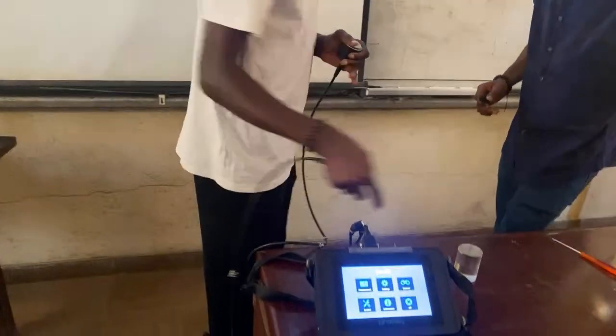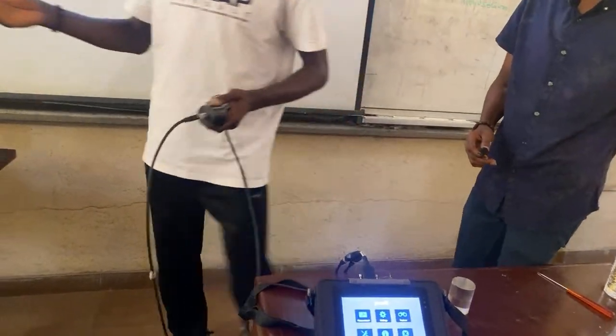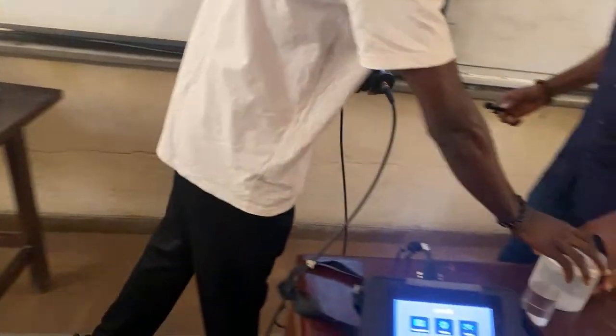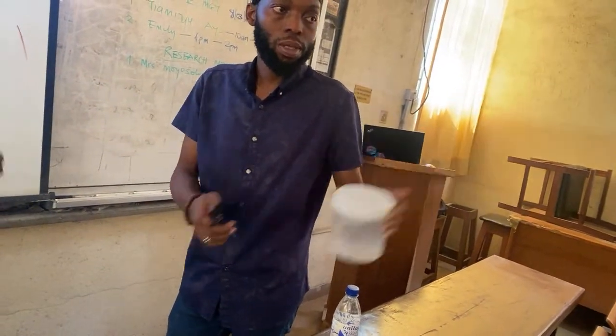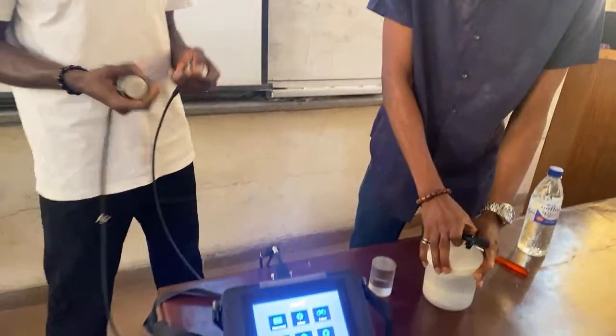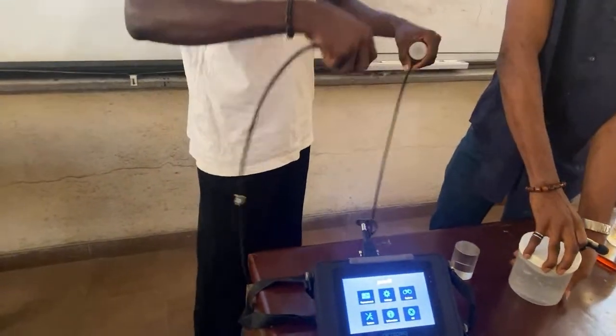Also, another thing, sometimes even after changing all these things and it's still showing error, you can just apply a little couplant. Couplant. You understand? A little one. So after changing the cable, after doing any adjustment and it's still giving you error, you can just put couplant on the connecting rod.